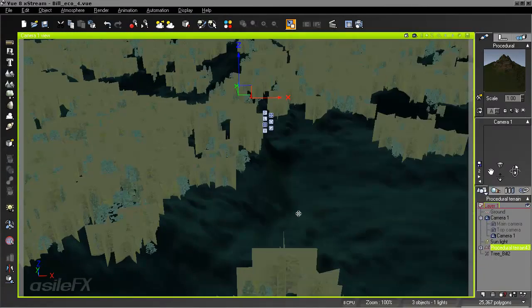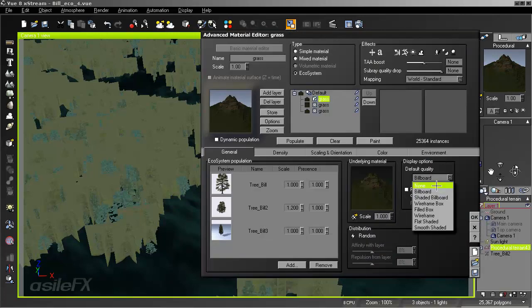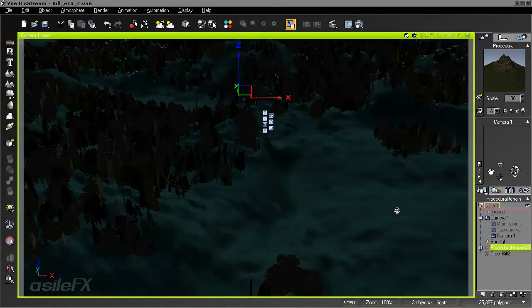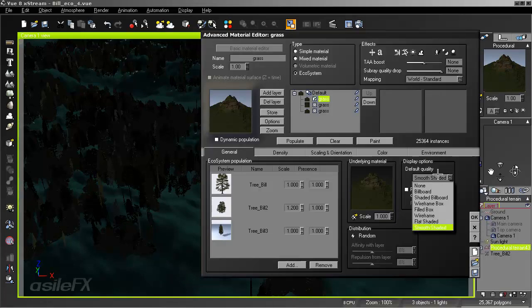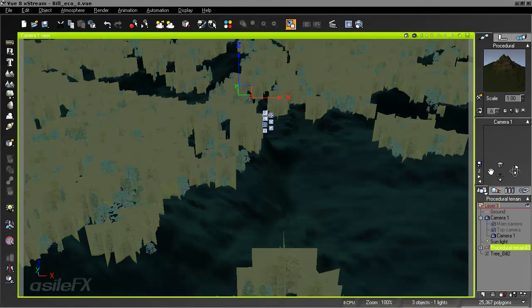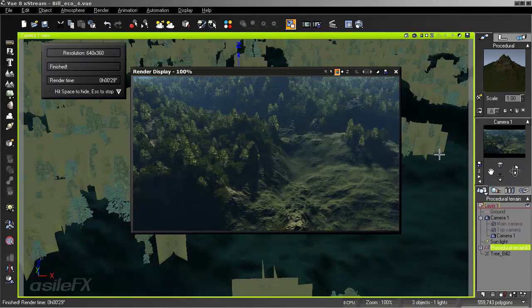We could pretty easily switch this over to smooth shaded mode as well, because they are just planes, one polygon each. The biggest thing to worry about is the textures themselves, which might slow things down. So just billboard mode will work alright. So now you can see the new billboard showing, which are the lighter green trees.